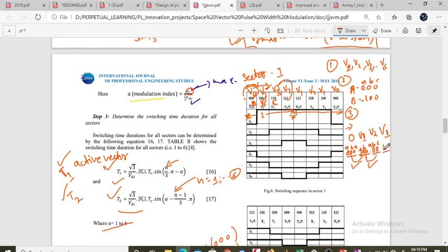And again for 1 0 0, the last one, then 1 and 0, 1 and 0 for A and C remain the same, only the B phase transits here again. So that means we can say, it doesn't matter if one phase transits again and again, but the point is that in consecutive switching sequences one phase should transit, right? So this is the point. Okay, so this vector is valid.